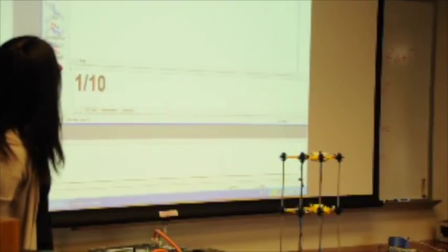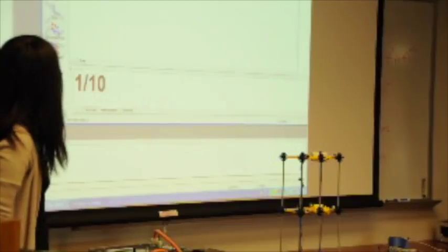So we have the plane, the line and the point. We want to go to the operate tab, and we want to create a coordinate system using those features. This will be the frame, and we will say, okay, what is the primary axis?